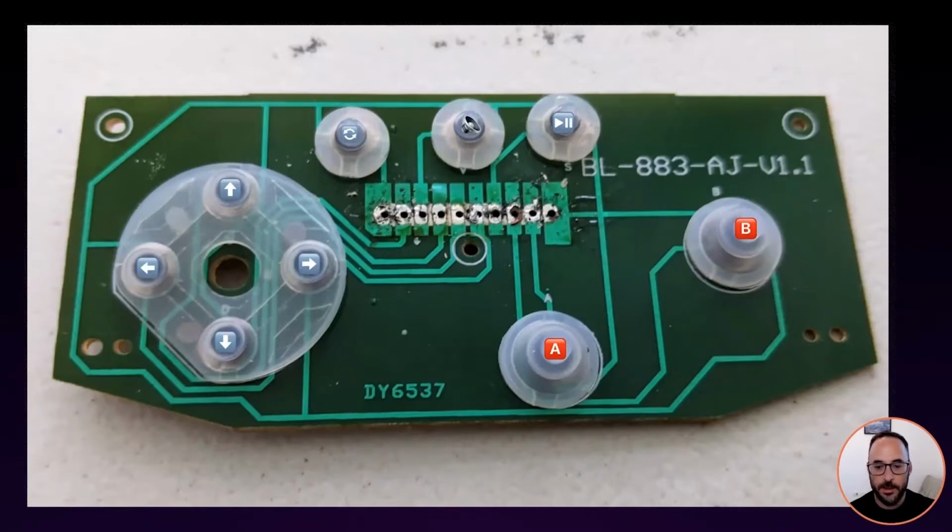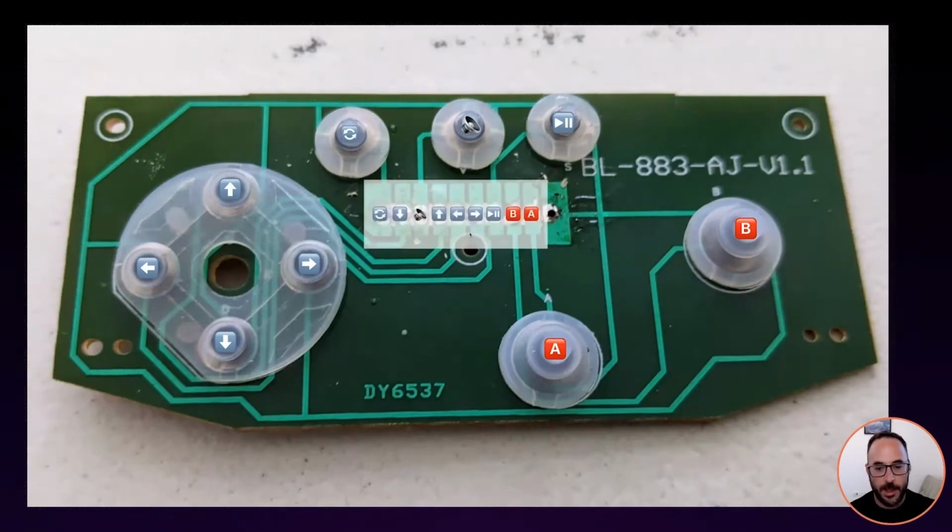Now, the pins in the middle is how this board is connected to the main controller board via a cable inside the machine. So by following this light green path on each of the buttons, I determined that each pin is associated with one button. Except, as you can see here, there's a mystery pin that's not connected to a single button, but rather is connected to all the buttons via the perimeter here, the light green path as well. So after a bit of Googling, I realized that this is the ground pin that completes the electrical circuit.